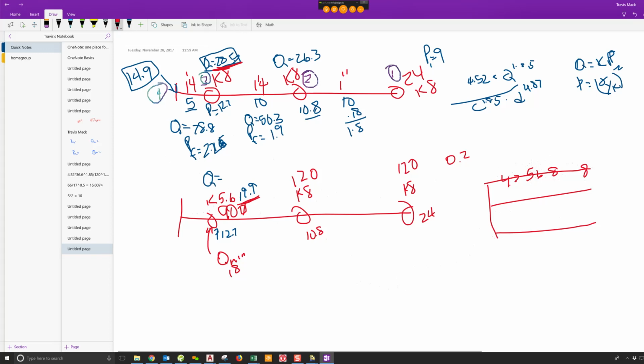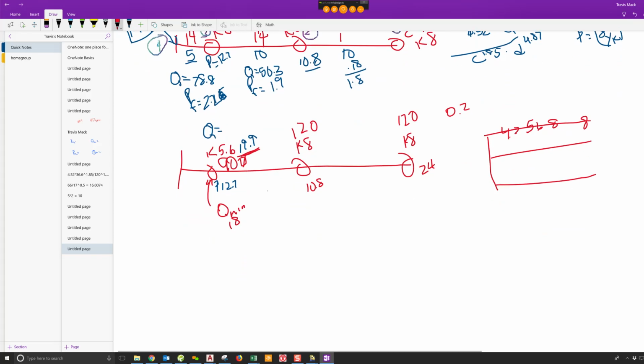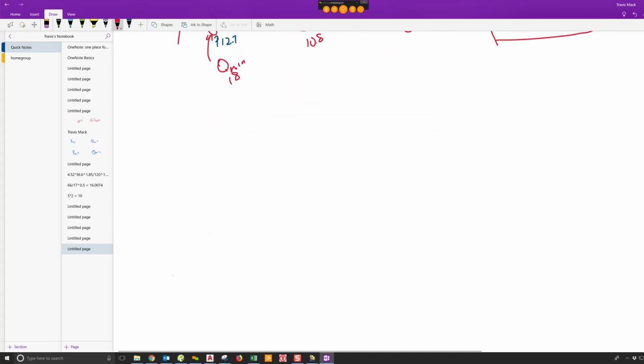So this is what happens when you mix the orifices, and this is where NFPA says, no, you can't do this because you're trying to cut down your flow, give your system less flow so your calcs have less pressure loss coming to this point. And that's the rationale as to why they're saying that you can't use K factors to balance flows. Does that make sense? Okay, cool. So a lot of guys don't understand that. It totally blows them away. Now, let's do something, the exact same thing.